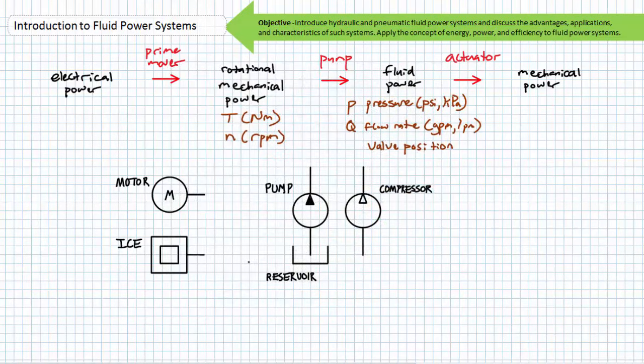When the prime mover turns, the shaft of the pump produces flow measured in units of volume per time, ordinarily gallons per minute or liters per minute. The load-induced opposition to flow is what creates pressure. If the pump is just pumping into empty space, there's no pressure, and to top it off, a rapidly expanding pool of oil on the floor.